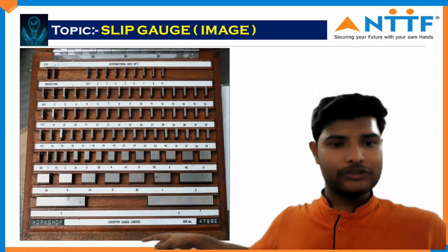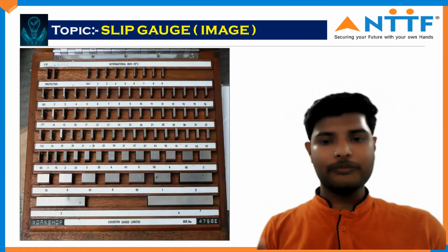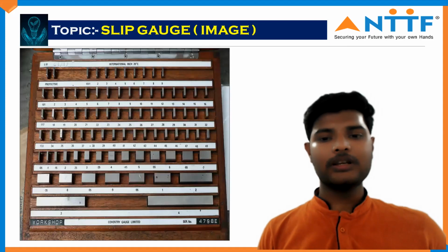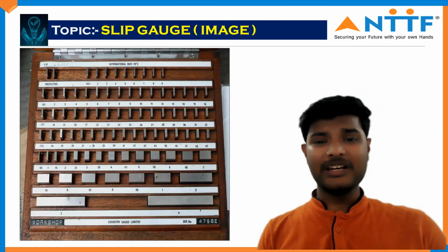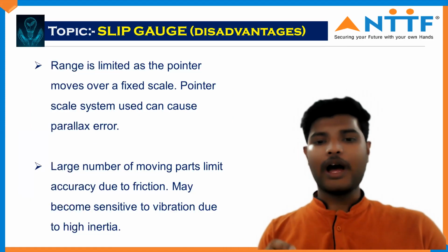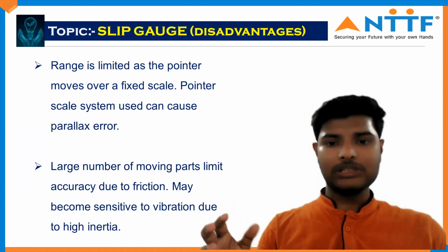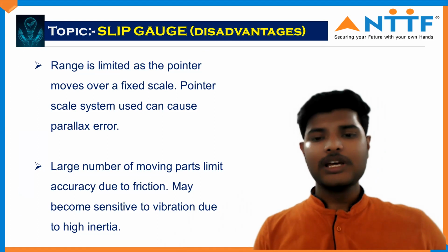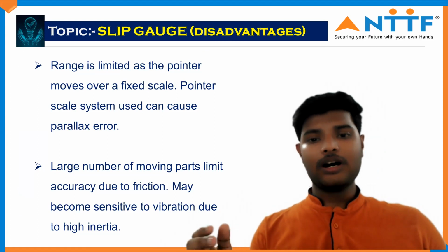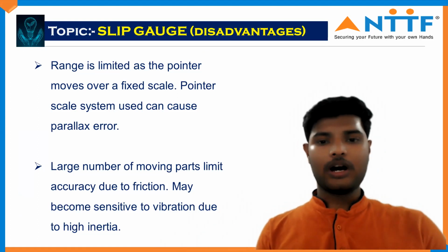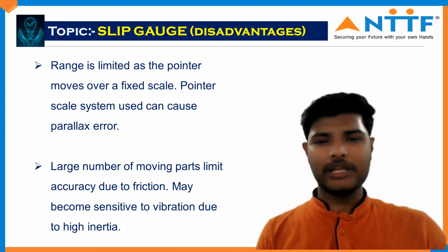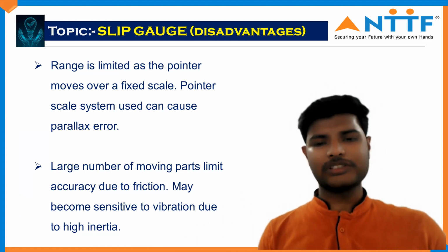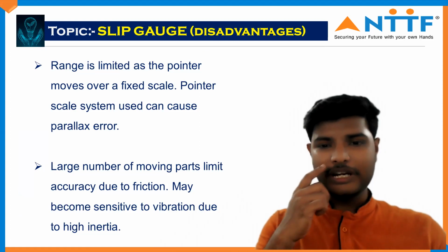As you can see in this photo, there are no bigger sizes. If I set a bigger workpiece in my machine, I couldn't get the precise length. If I take a 200 or 300 workpiece, I couldn't set it with this accuracy for machining. So this has a small error, because this kind of slip gauge is small enough that we couldn't set it for bigger lengths.